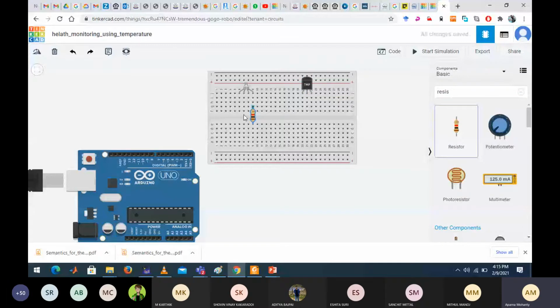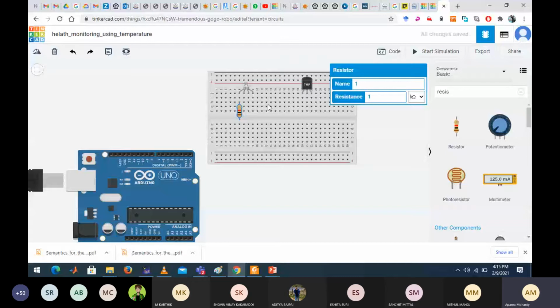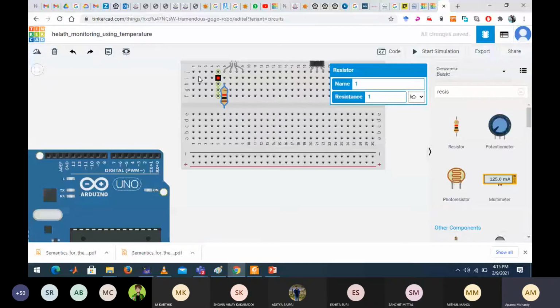I hope all of you already know about this breadboard, the voltage potentials. So just see here. I've just zoomed in. You can see 1, 2, 3, 4 written vertically along all these columns. The moment I click here, there is a green line getting connected to all the points. That indicates all of them are in the same potential. This entire second column is in the same potential. So that's how the connections are done in a breadboard.